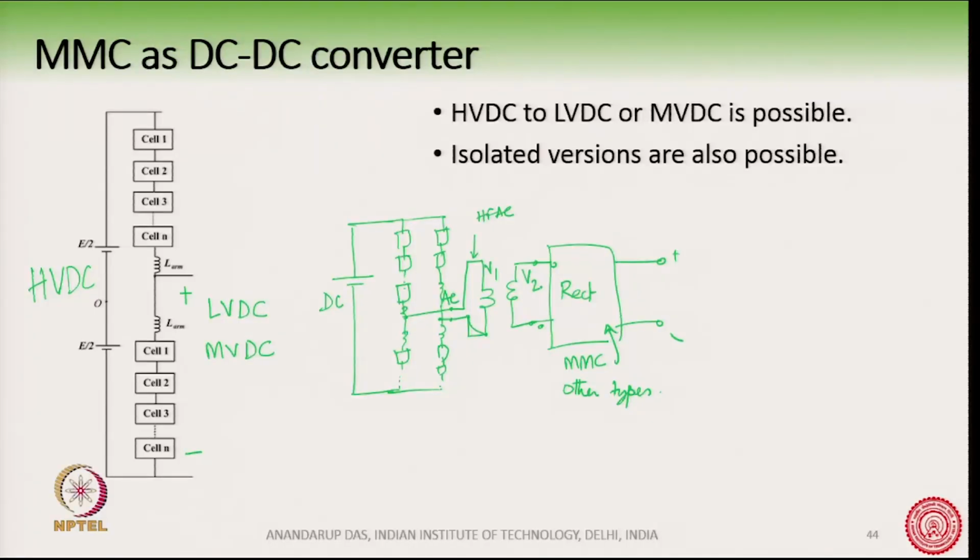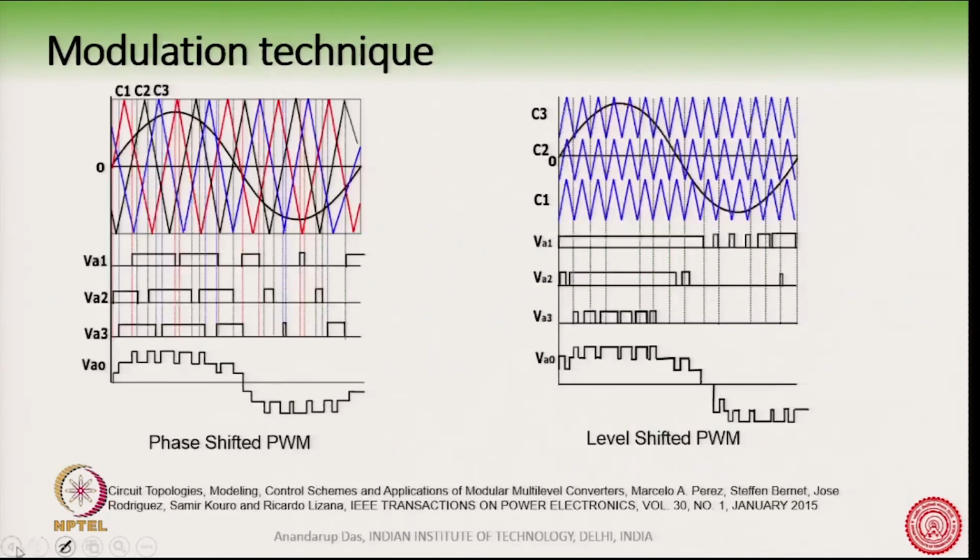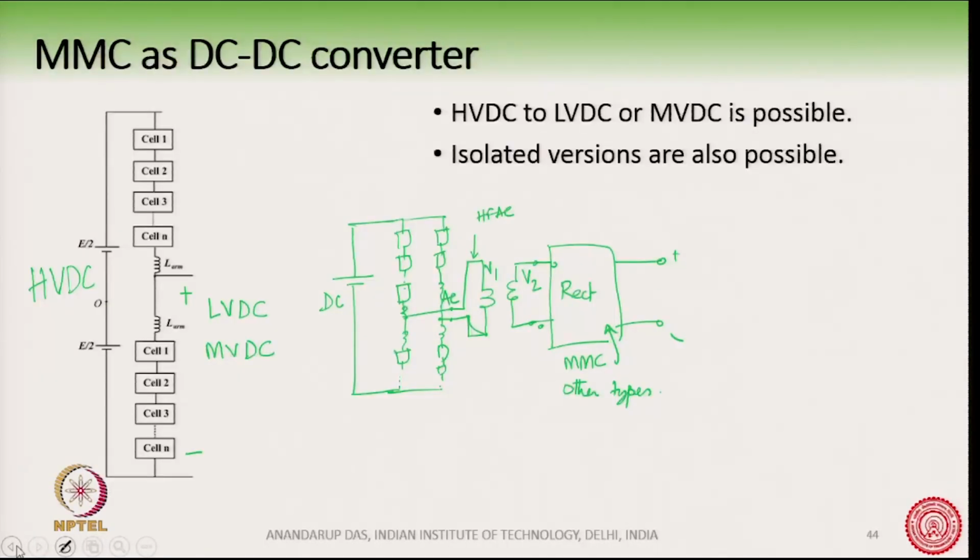So, what I want to stress here is that a large number of possibilities exist when MMC blocks or MMC cells are used, and the way to analyze it is to think of these cells working together as controllable voltage sources.